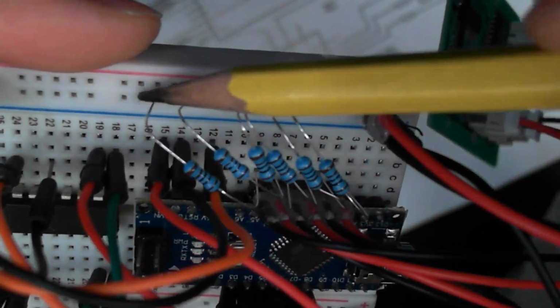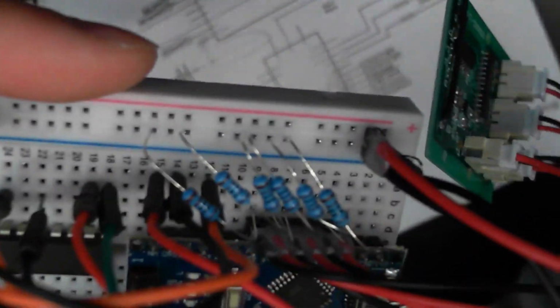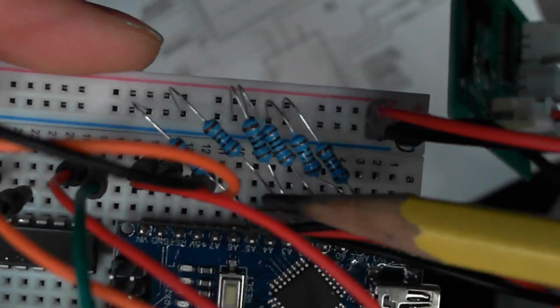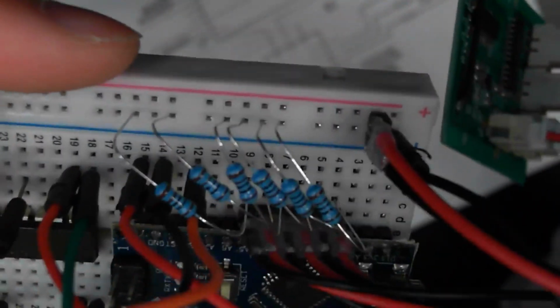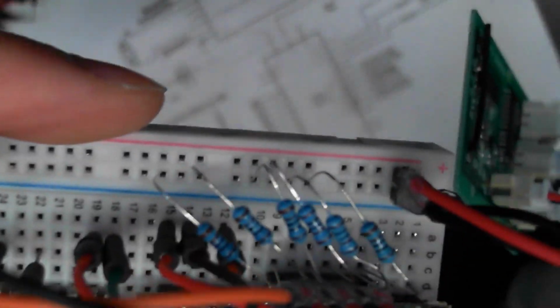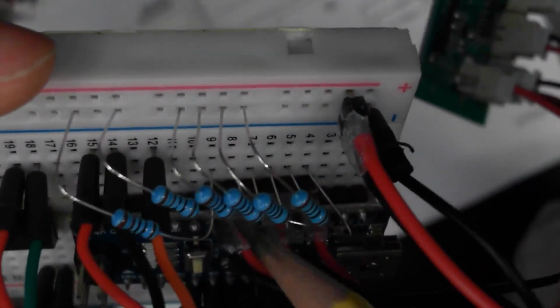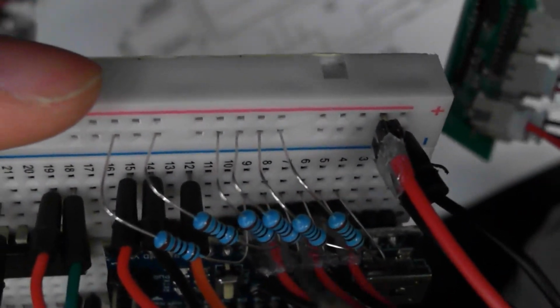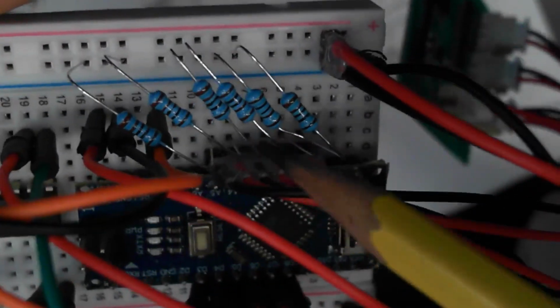It's okay if these ones touch on this side of the resistor because they're all connected to the same ground, so that side doesn't matter. It's just the side that's on the Arduino that must be isolated. If it helps, you could put some pieces of paper in between or tape or something to isolate them. But just keep in mind, if your soccer bot is acting strange, it might just be because they're touching on these leads here.